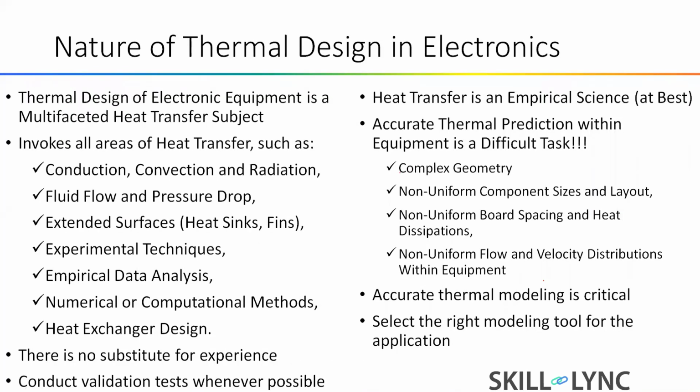Once we know everything, we have to understand the components and the nature of the thermal design. Electronic equipment involves a multi-faceted heat transfer subject. Any electronics involves all the areas of heat transfer, such as conduction, convection, radiation, then fluid flow, pressure drop, and the use of extended surfaces for cooling purposes, like heat sinks and fins.